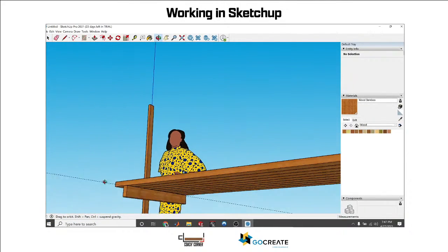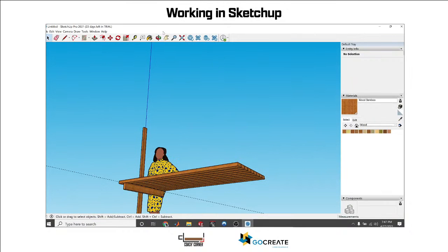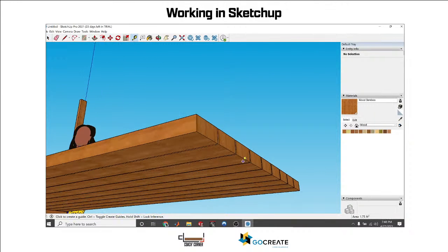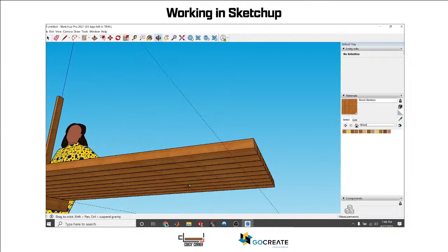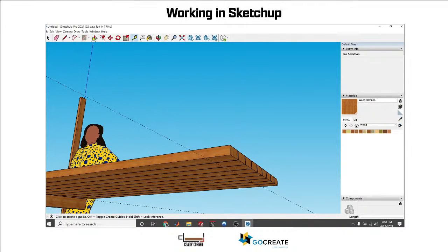All right, let's do our 4-inch tool again. So we grab our tape measure, grab on this line here, come in, 4 quotation marks, get our 4 inches, and then we want to move this, but we do the control key and click.